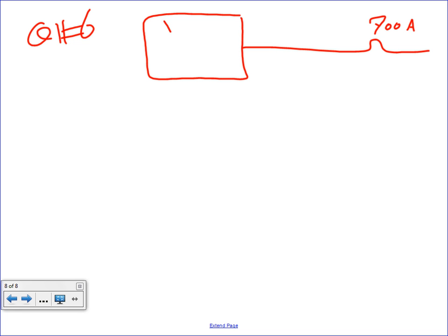Look what I have. I have a service of 700 amp. The demand load that's calculated on this service is 650 amp. Meaning if it's a demand load, guys, it's already multiplied by 1.25 or derated, everything is done. All the calculation done, solid. So you have the load and the amps and you need to size the conductors. The question is, what size 75-degree copper conductor would be required if paralleled in two?